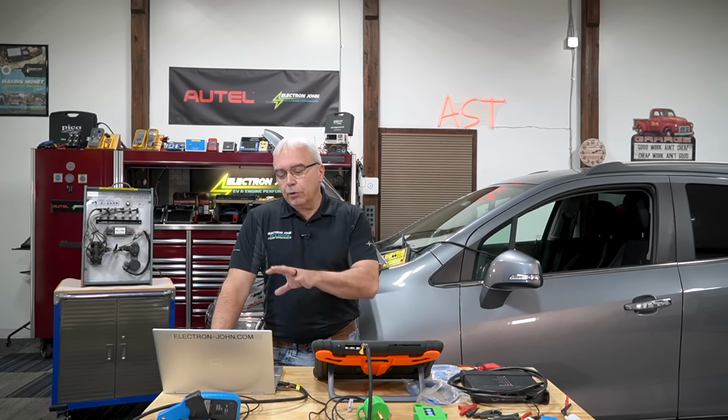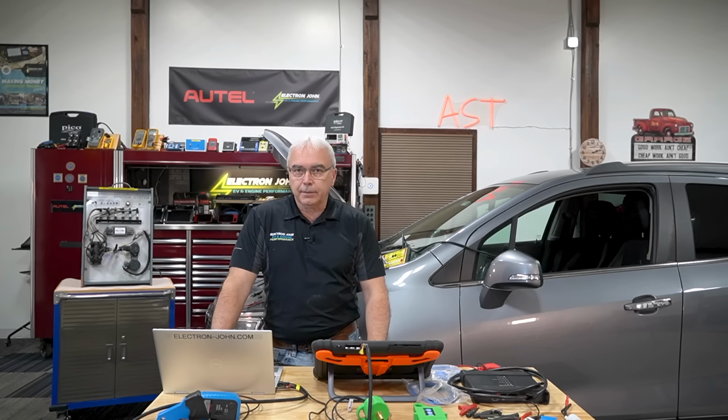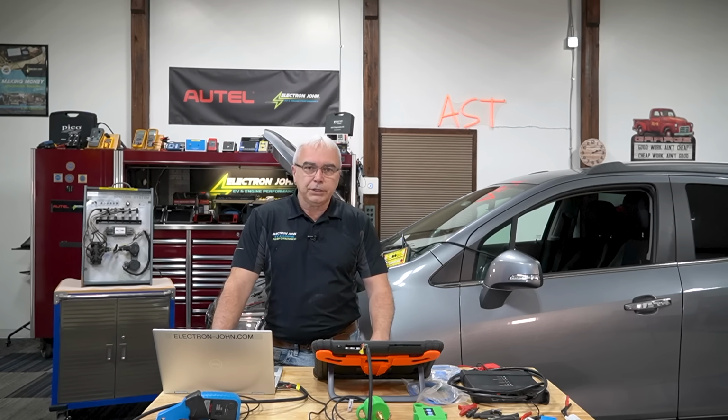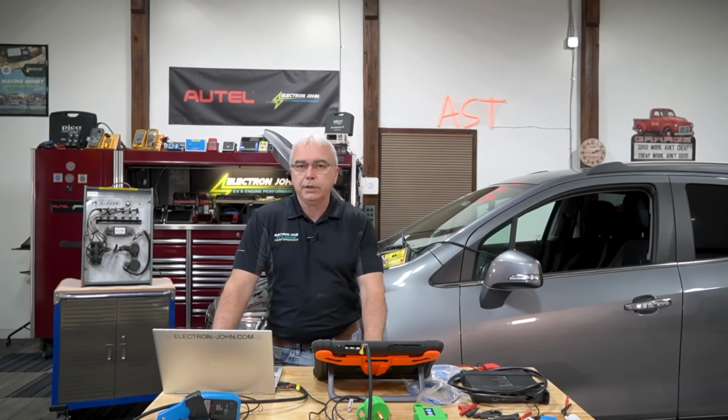Now, if I zero in on looking at those 6 main lines of data, and as we go through this little presentation before we start turning it over live to this vehicle, you'll kind of understand what my thought process is and what I use those 6 lines of data for. Now, I'm not saying that if I have a specific diagnostic trouble code, say for an EVAP system related problem, I might look at some of those lines of data, but by the same token, if I have a code, I'm probably going to be using a whole different diagnostic process because the computer has generated a code for me.